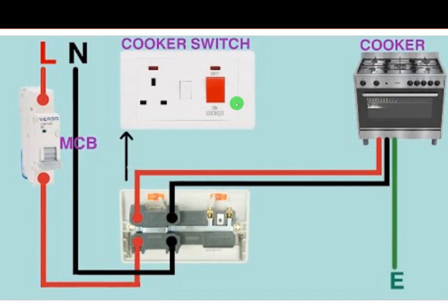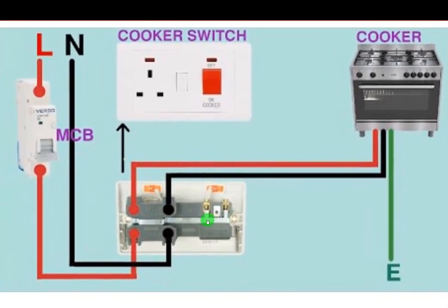Meanwhile, the power of the cooker is rated for 45 amps or 32 amps, depending on the type. So if the entire cooker here is rated for 45 amps and here is 13 amps only, you are using 45 amps to power a 13 amp outlet. You see that it will go bad easily, right?